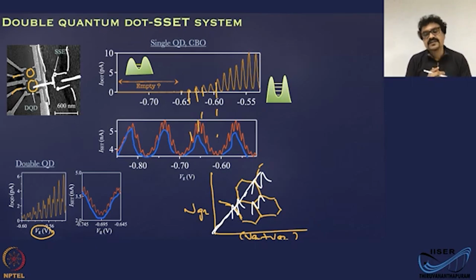But at the same time, this single electron transistor comes with an extra expense, that is, these are separate systems, and these have a lot more gates, and it's very sensitive because they are another Coulomb blockade device as opposed to the quantum point contact, which has a very large linear regime, whereas the single electron transistor is sensitive only on the sides of the Coulomb blockade oscillation, which is a much narrower regime where the device is sensitive. Okay, that is one thing.